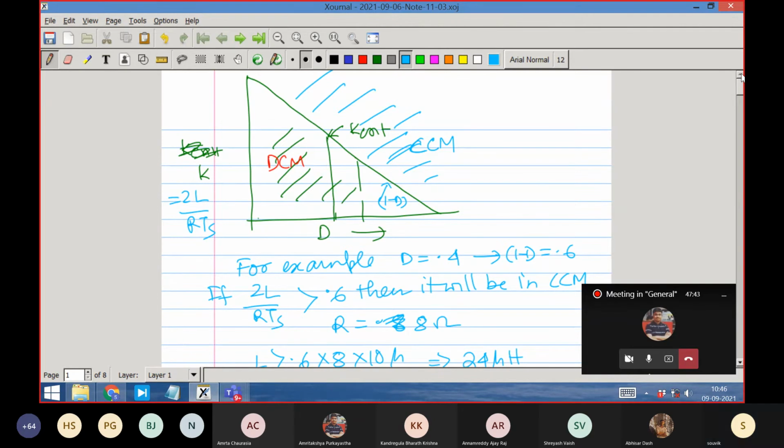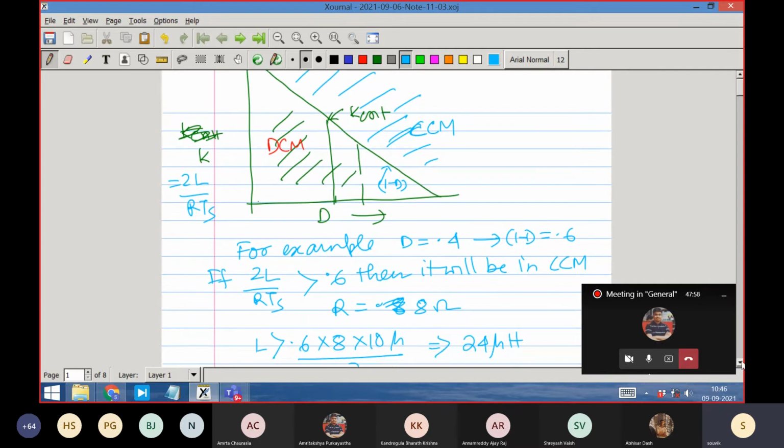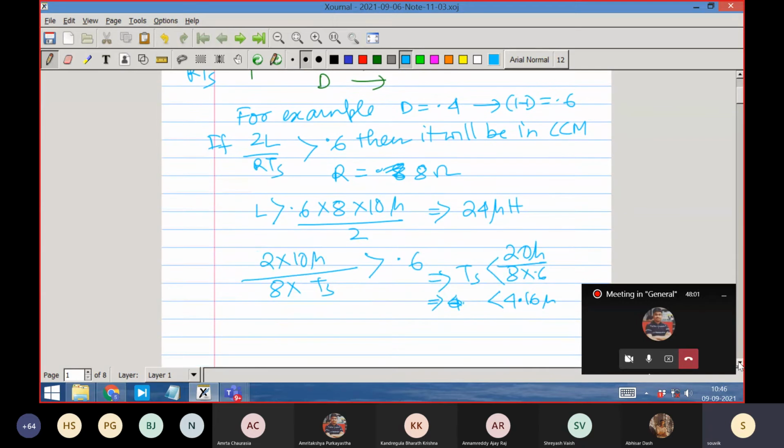So in the continuous conduction mode, we have seen how this can be obtained. Now you will see that in continuous conduction mode, the voltage ripple expression is slightly complicated. I will sketch the waveform and tell you to determine it. I will not do it now. So what is the approach we will take? Anytime we have to find out voltage ripple, we have to first sketch the capacitor current, because that is the cause. C dV by dt is IC.